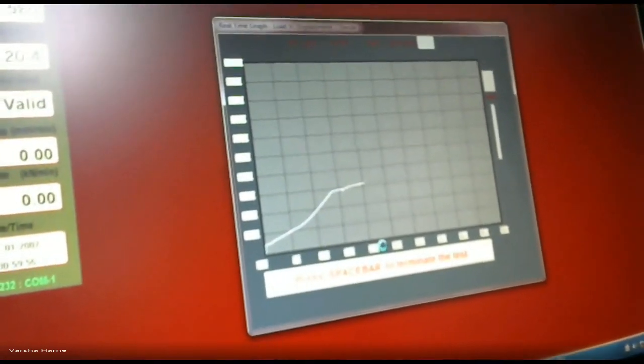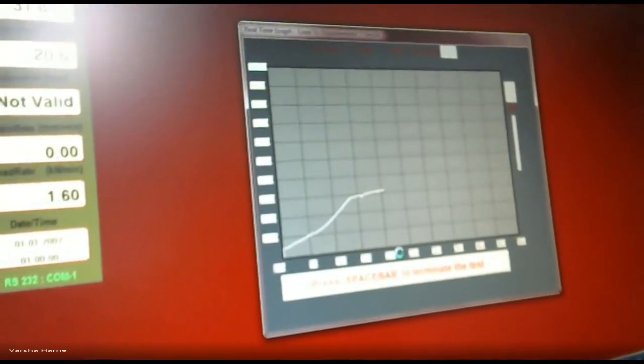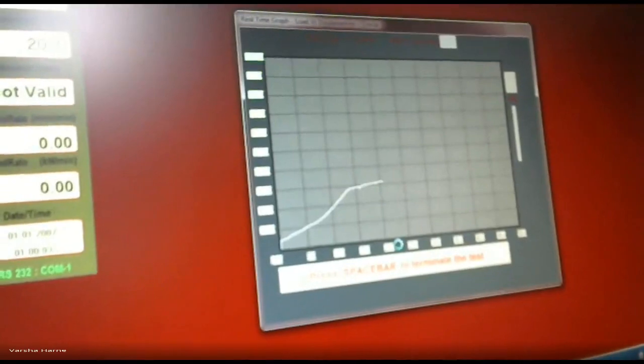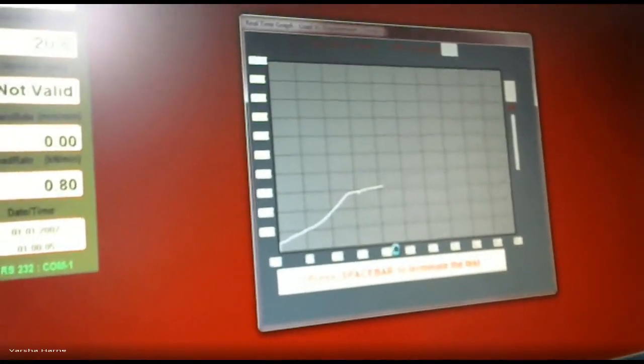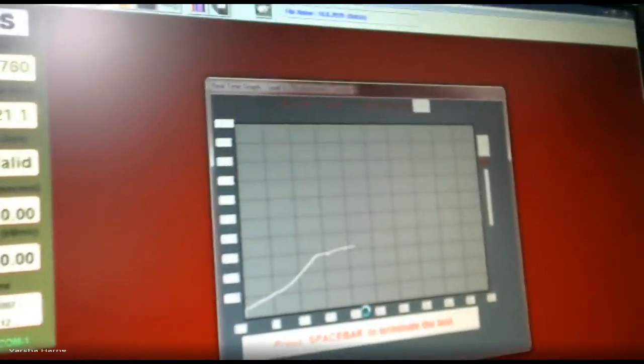Because of the shear criteria, failure occurs according to that 45 degrees, so naturally we get the specimen in two pieces having two different shapes, one is cone and the other is cup. We have to check whether it is right or wrong after performing this practical.